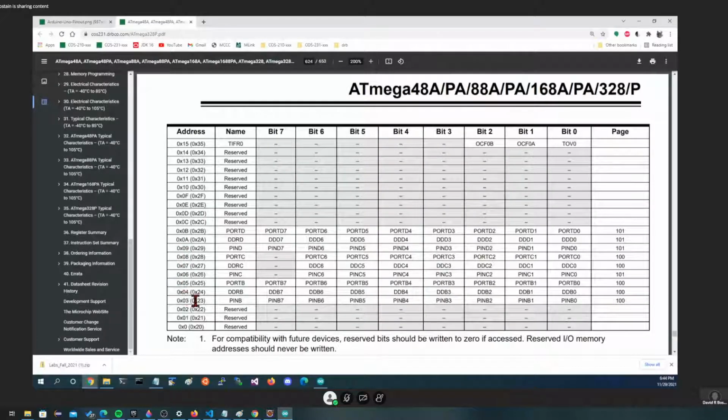But if you look at them in the header files, they're always going to have the memory address. So in order to use those instructions on these particular registers, we have to first of all subtract away hex 20, which gives us the real I/O address in order to use those instructions, which is exactly what we did in the instruction we wrote. As you recall, see if I have that still open here on the screen.